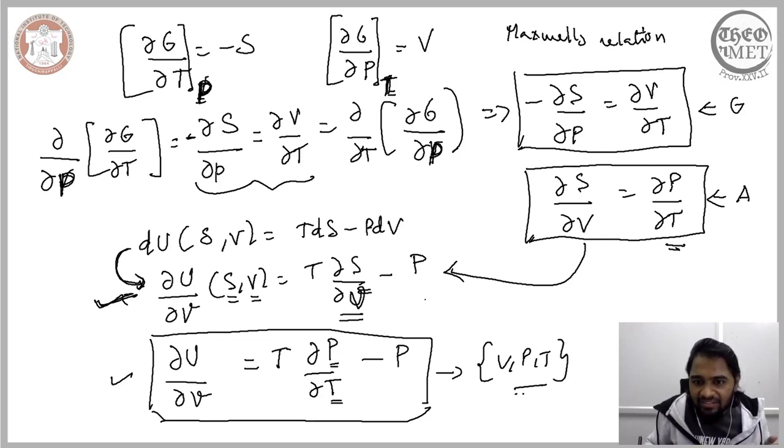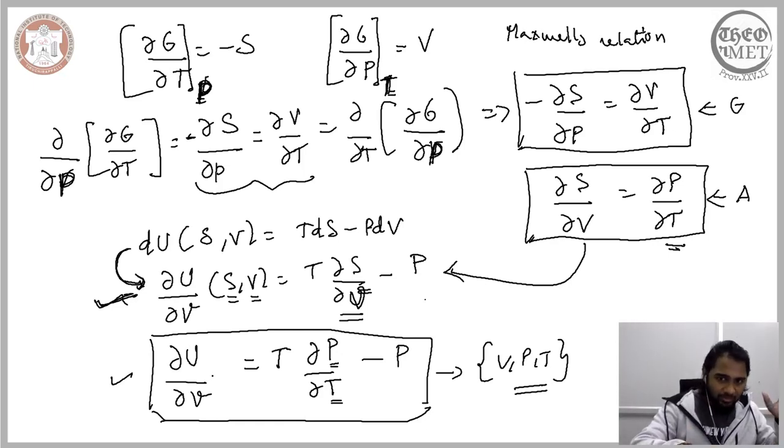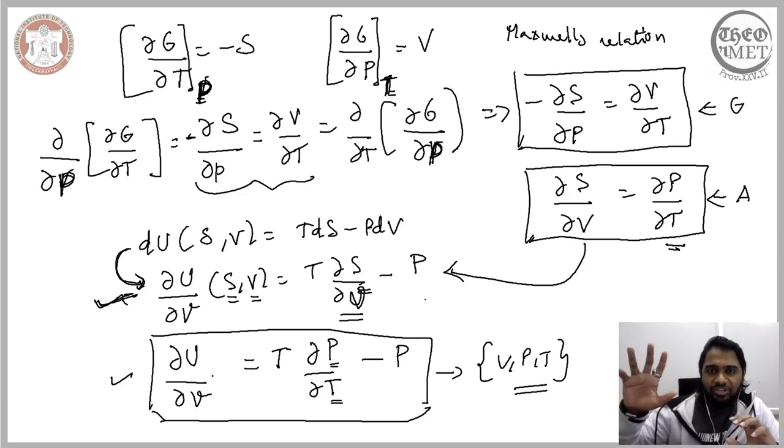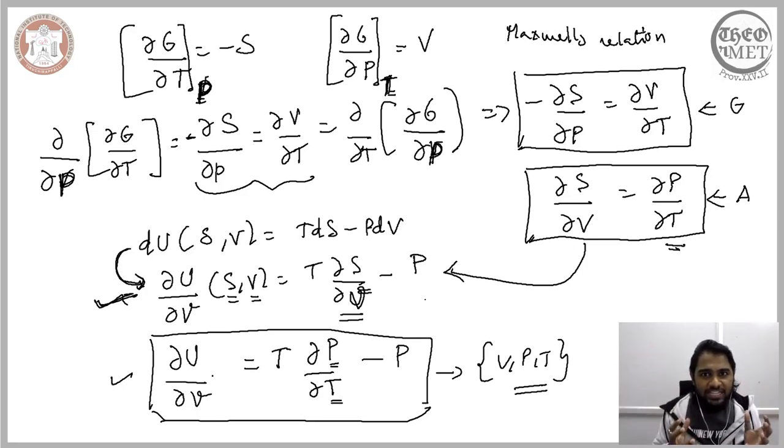So these are the fundamental variables that dictate the change in the internal energy. So we set out to remove the influence of entropy, and now we have arrived at it. We have now established, or derived, an expression wherein the change in the thermodynamic function is no longer dependent on entropy. Without measuring the change in the entropy, it has now become possible for us to quantify the change in the internal energy when there is a change in volume.